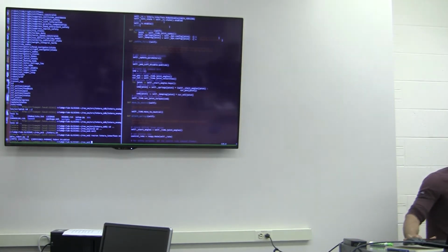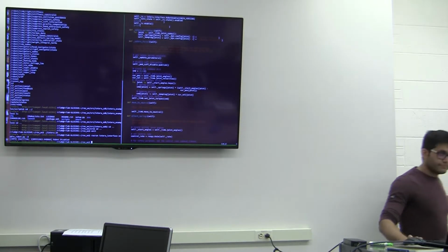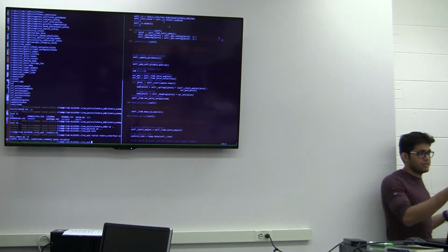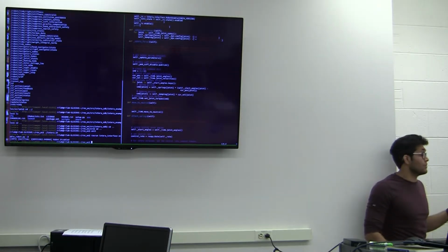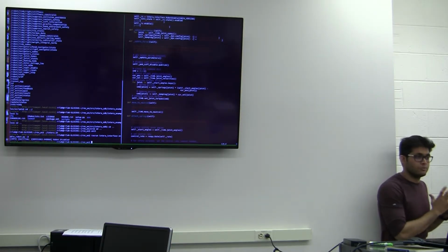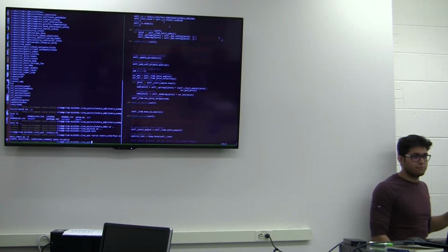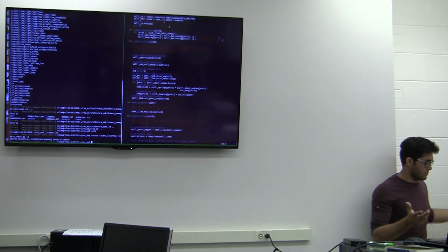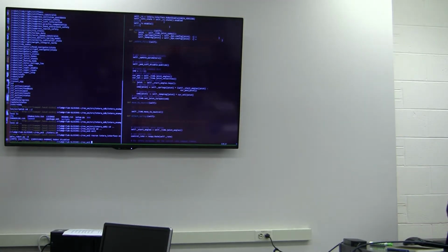Again, the final thing is the safety button. It's very important because you'll find most robots have a safety feature or safety button. If the robot goes uncontrolled and you don't know what to do, press it. That's it. Just simply press it. It will stop the robot at that state and stop all the axes. You'll be perfectly fine. Don't worry. Then just call one of us. We'll enable it, bring it back and configure it again. But always press it if something goes wrong.